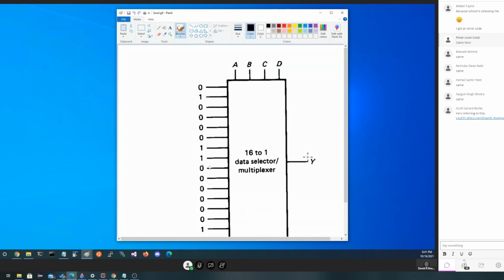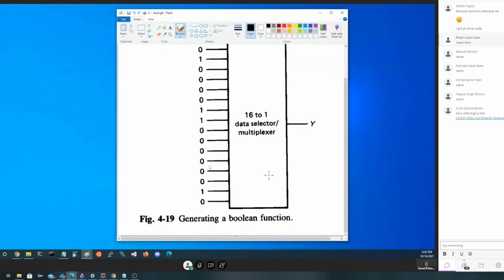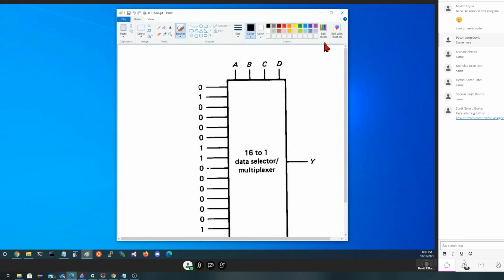And then I'd repeat 0, 1, 2, 3. And if on the other end I had something called a demultiplexer, DE multiplexer, it could take and return back from 1 bit to the original 16 inputs that I had. So I'd be able to encode and decode to a single stream some parallel data into a serial stream and recover it using a multiplexer and demultiplexer. Right now, however, we're going to focus in on using this thing to generate a Boolean function, because we're going to find that that's kind of a handy thing to be able to do.